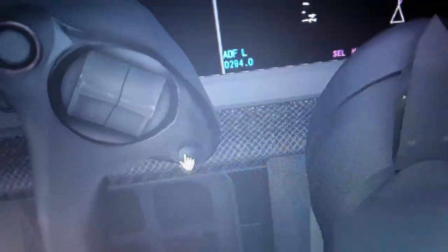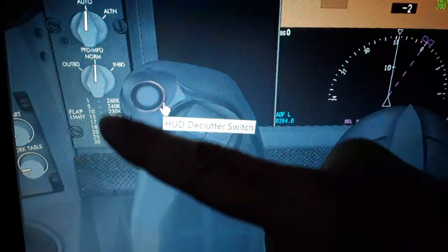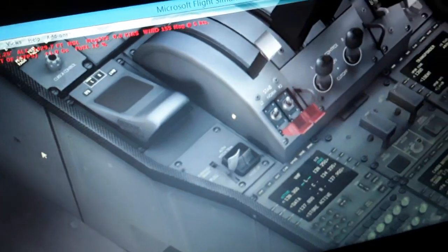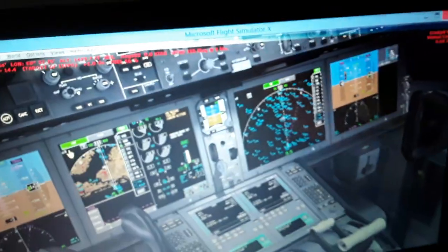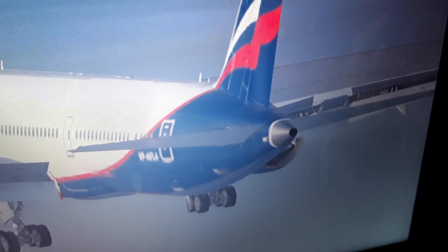We have also the autopilot disengage switch over here, and the head up declutter. Also the flaps speeds here, limits, some engine display. So over here, you can see the position of the horizontal trim stabilizer, because when you trim you move the elevator up or down like this. You trim a position of the elevator. So you can see the movement, elevator descent or elevator climb the aircraft as you fly. So you have the aerodynamic effects. You can also move the yoke instead of trimming the aircraft.